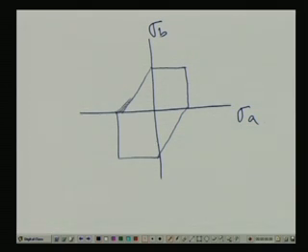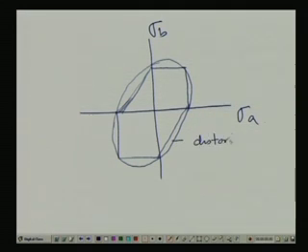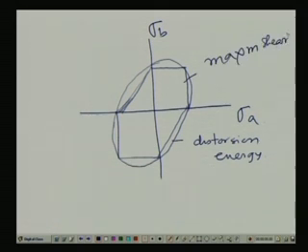If we superimpose the distortion energy results onto this, you find that the maximum shear stress theory is enveloped within the distortion energy theory.